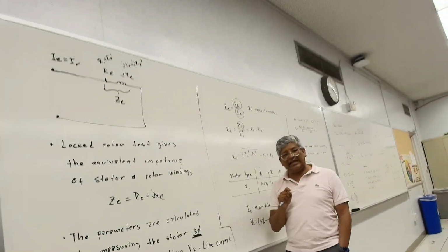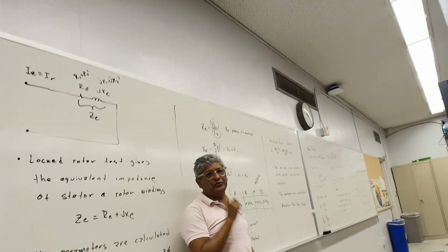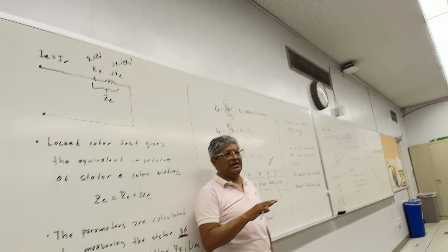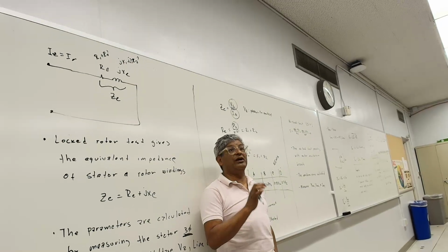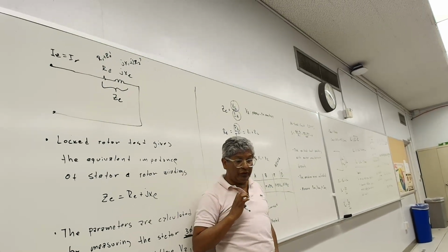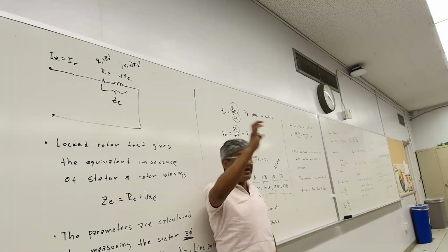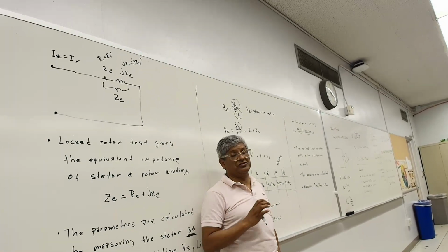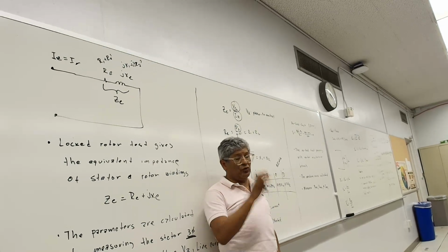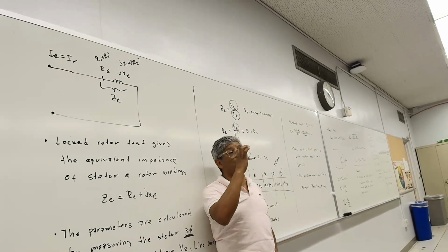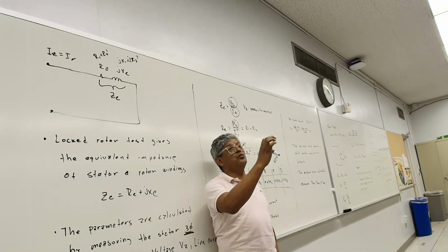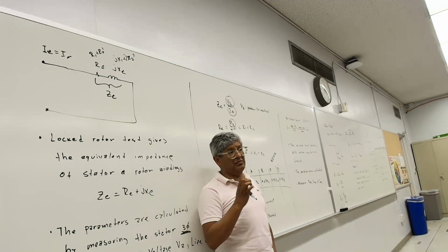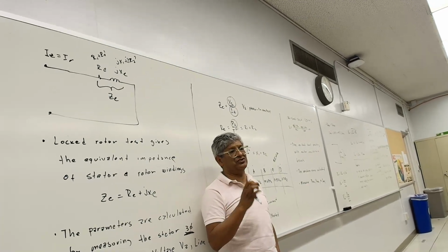I mentioned this in the last lecture, Maria, you remember when I said that for testing purposes, that's fine. But in real life, once you have the motor doing the work you need it to do, you never want to run the motor at synchronous speed, because induction machines are asynchronous, right? For them to do the work, you have to slow them down, or they have to run behind their synchronous speed, the speed of the rotational field, right?